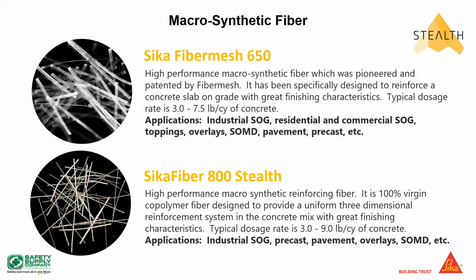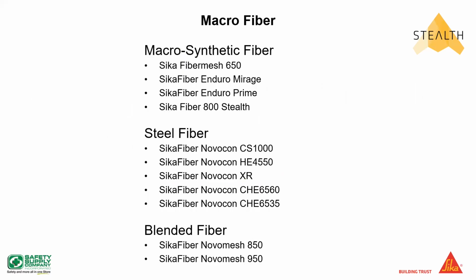Of course, if you have it, you can burn them off. What I will say is take caution when burning off fiber anytime you do it. Typically that's going to be macro fiber, because you don't want to shock the concrete with extreme heat. So you don't want to hold your torch on the concrete any longer than you absolutely need to. So anyway, just a neat little note.